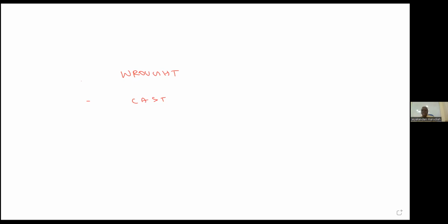Okay, right. Coming back to physical properties, now chemical properties, chemical composition. What is the maximum carbon percentage allowed in the welded construction? As per Section 8 and 510, 0.35. 510 has another requirement: above 0.3, preheating is mandated.